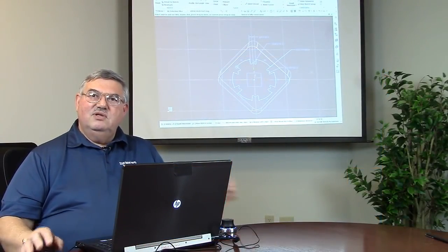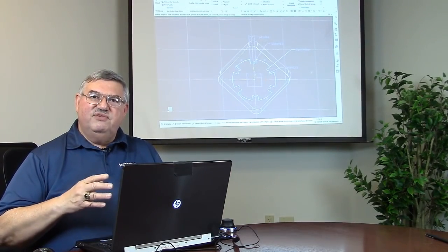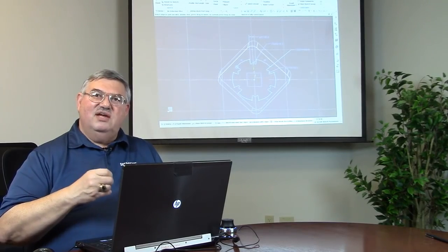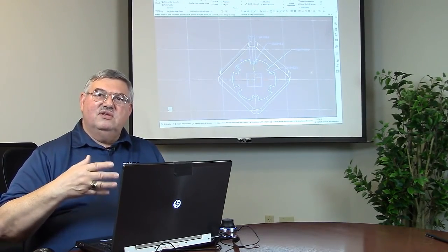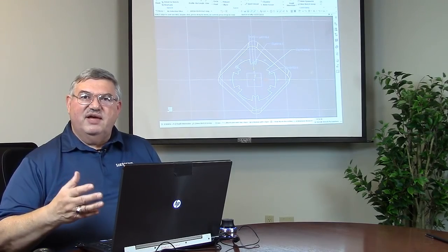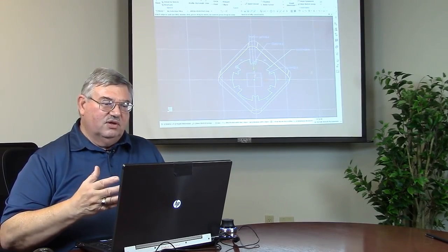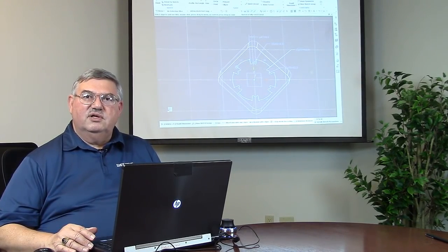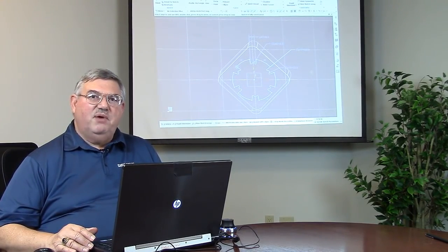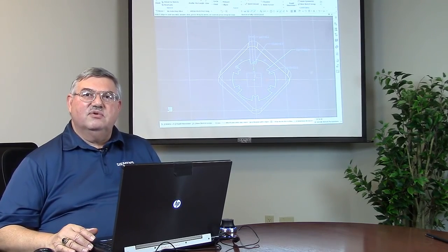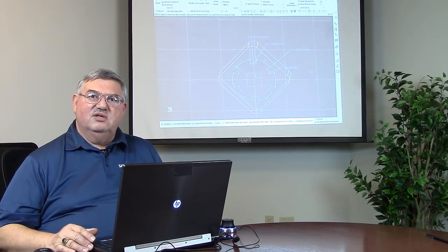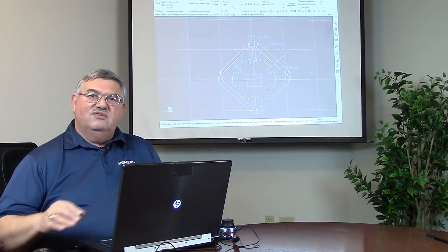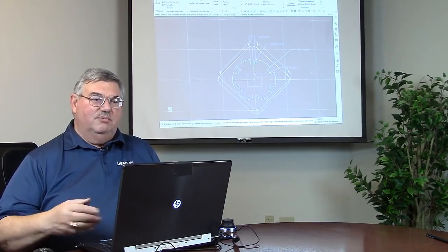So I can use this scalable group feature to help modify existing sketches when I need to do it using a scale factor, which was the goal here. Of course, you could also use these scalable groups just for controlling simple objects as part of a sketch. In other words, leave them grouped as a scalable group, and then you could modify it any time that you wish. But in this case, I was using it as part of a workflow to edit this model.